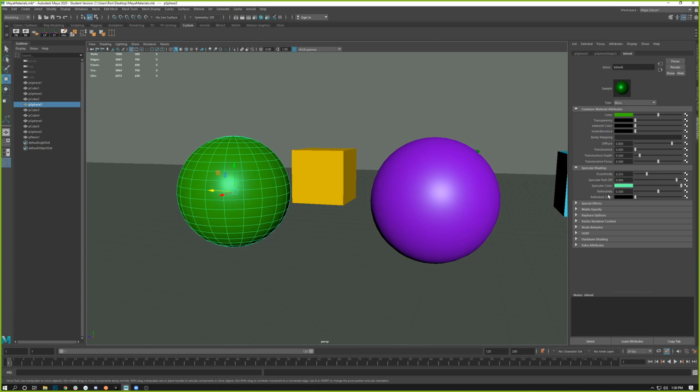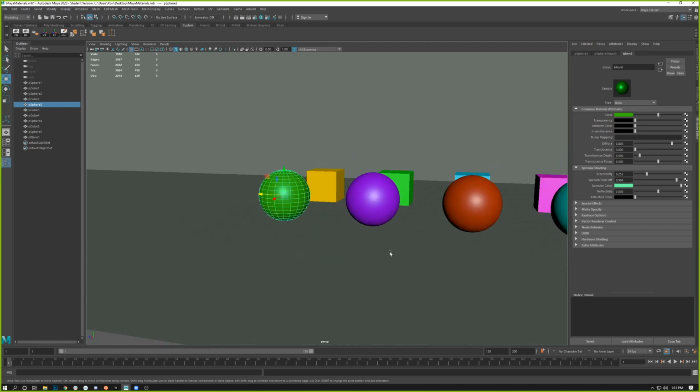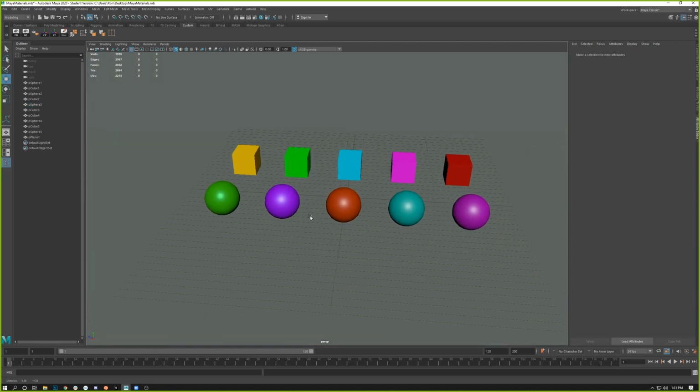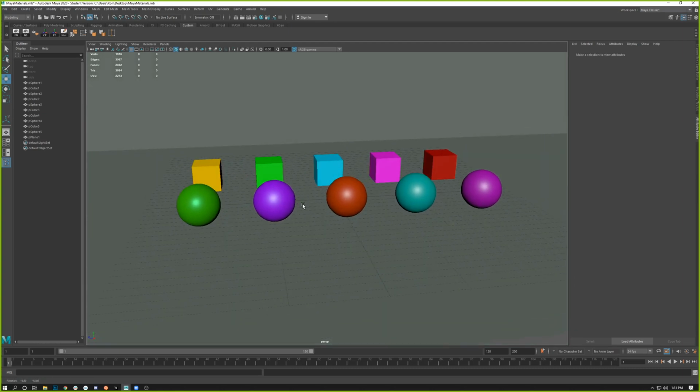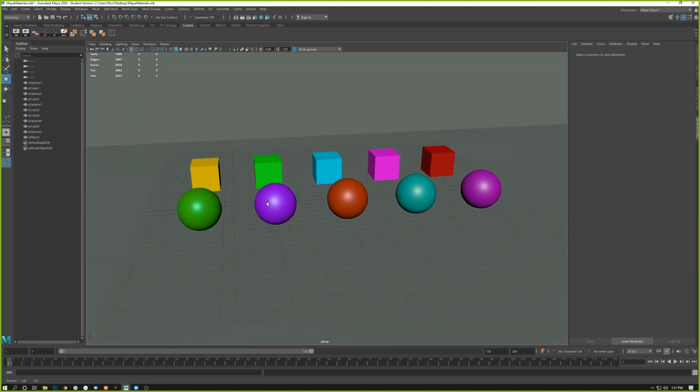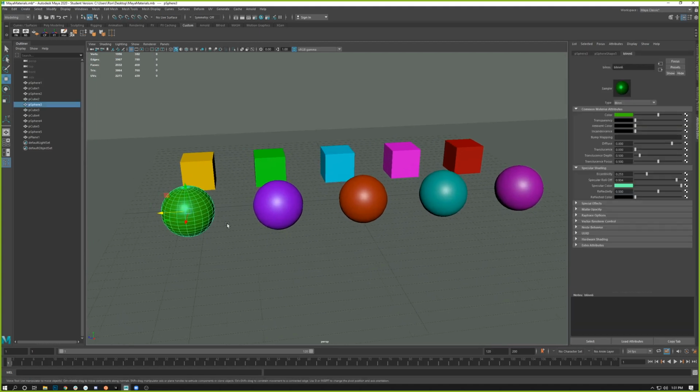You probably don't have to worry about this attribute with this exercise, but again, if you start rendering things out and maybe you are using the Arnold renderer, because you could do this with the Arnold renderer, this reflectivity attribute can be toned down to help reduce how reflective it is. What are you seeing inside of it? Again, that's more advanced rendering. That's definitely another whole topic series. So some of these properties are more basic, and some of them I would classify as, you know, time for another lecture series. All right, so that is the basics of the materials there.